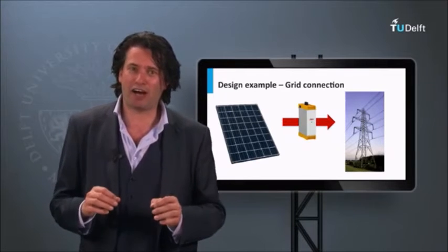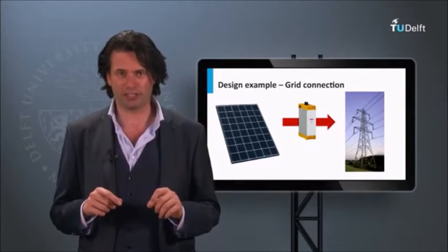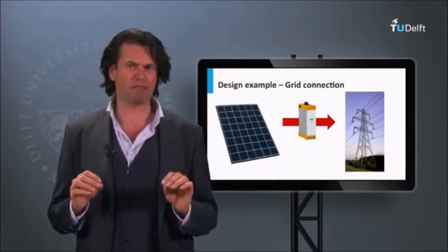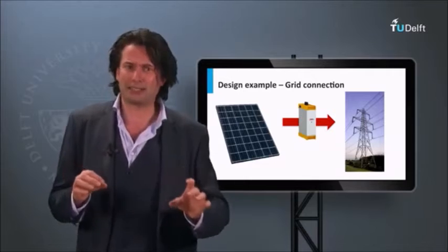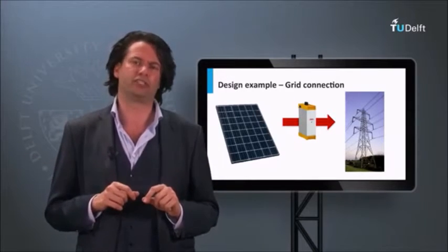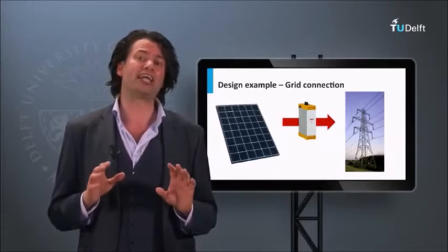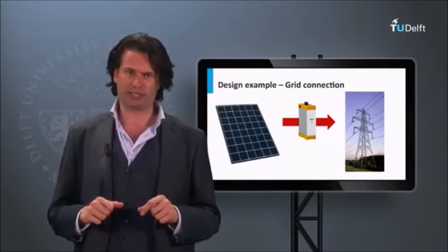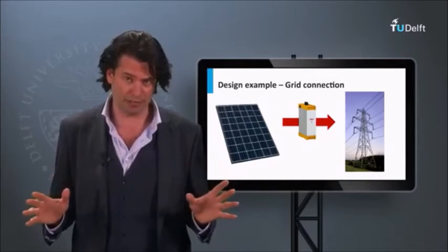Now, I must clarify one thing about the grid-connected PV system. Usually, the amount of PV panels or the rating of PV panels need not be exactly as per the load requirements, like it was in the standalone PV system. This is because any excess or deficit of PV power can be compensated by the grid that is present in the scenario anyway.